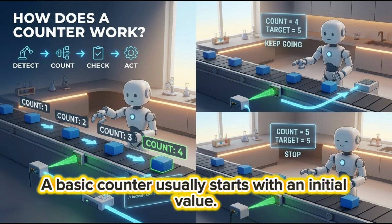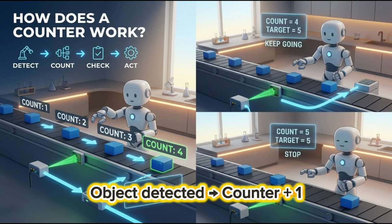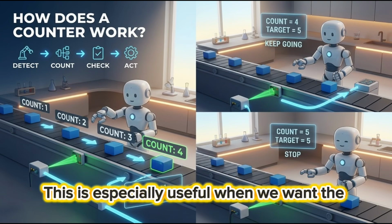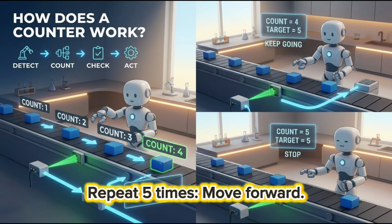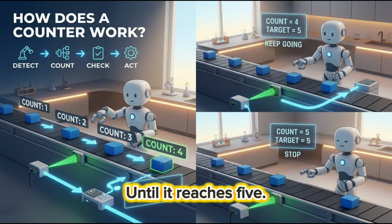How does a counter work? A basic counter usually starts with an initial value. Most of the time, we start with counter equals 0. Then, whenever the event we're monitoring happens, we increase the counter. For example, object detected, counter plus 1. So, 0 becomes 1, 2, 3, 4, 5. The counter keeps track of the number of events. This is especially useful when we want the robot to perform an action a specific number of times. For example, repeat 5 times, move forward. The counter helps the robot know, okay, I've moved once, then twice, 3 times, until it reaches 5.